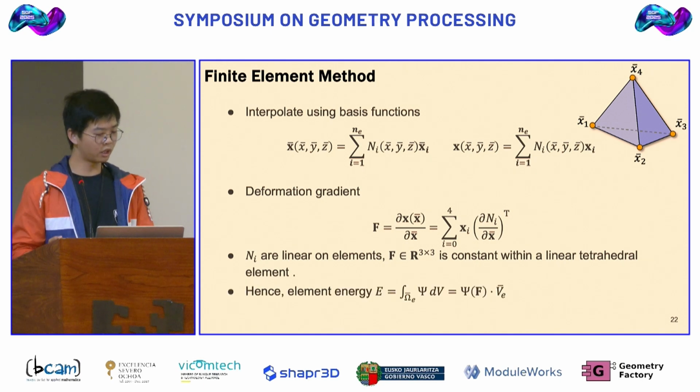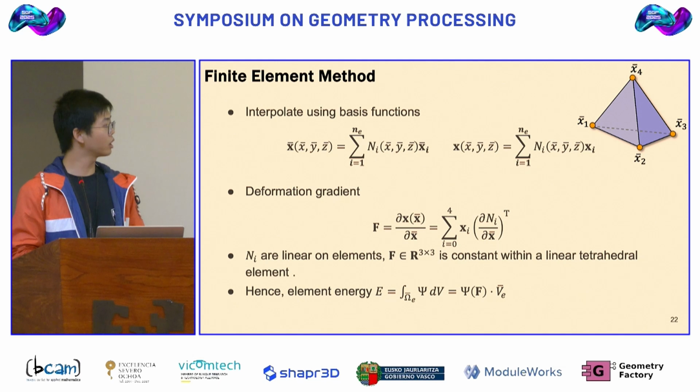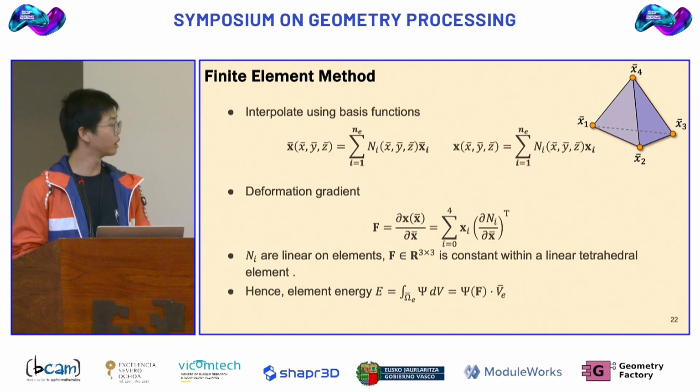So if we need to compute the element's energy, we have to integrate the energy density function over the domain. Since this deformation gradient F is constant within the linear tetrahedron element, the energy is basically the energy density function times the rest volume.